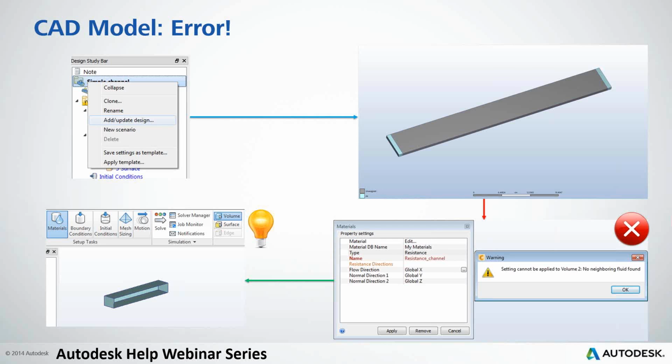You just need to make sure that you're going to have a node that isn't going to have a boundary condition on it when we go to calculate, because you don't want to have your zero pressure lined up right next to your resistance. Although the zero pressure isn't as bad as if you've got flow rate or something like that, where it's just going to cause pressure to go a little bit nuts right on the inlet of a resistance.